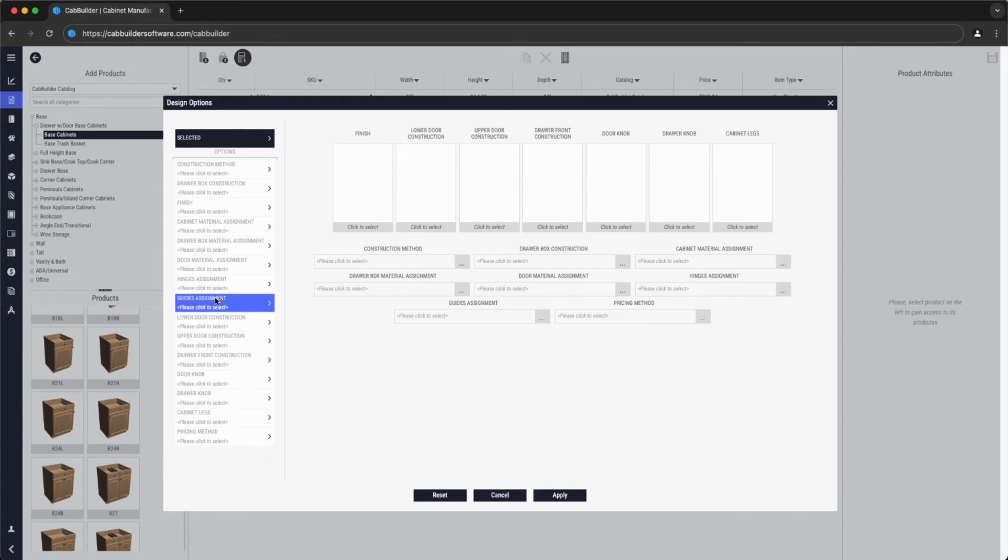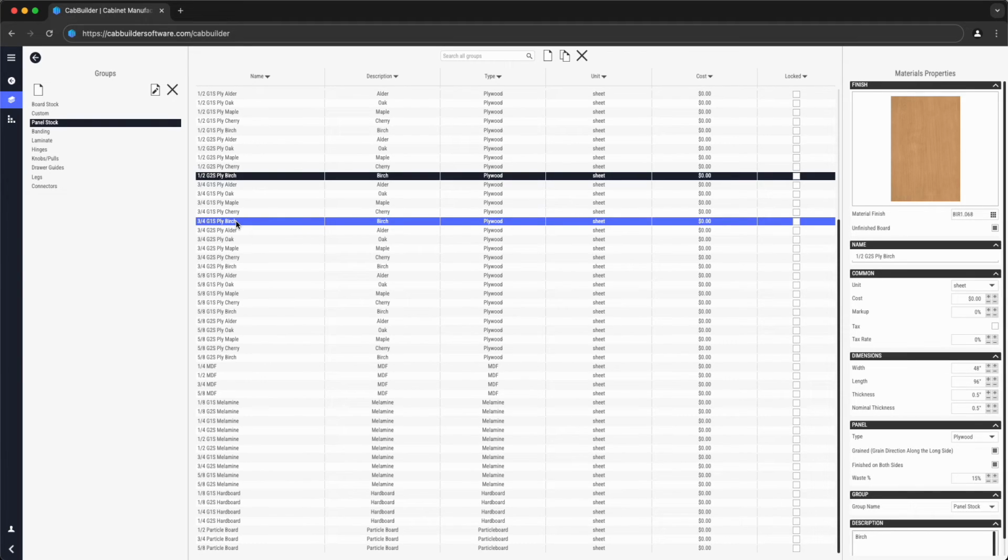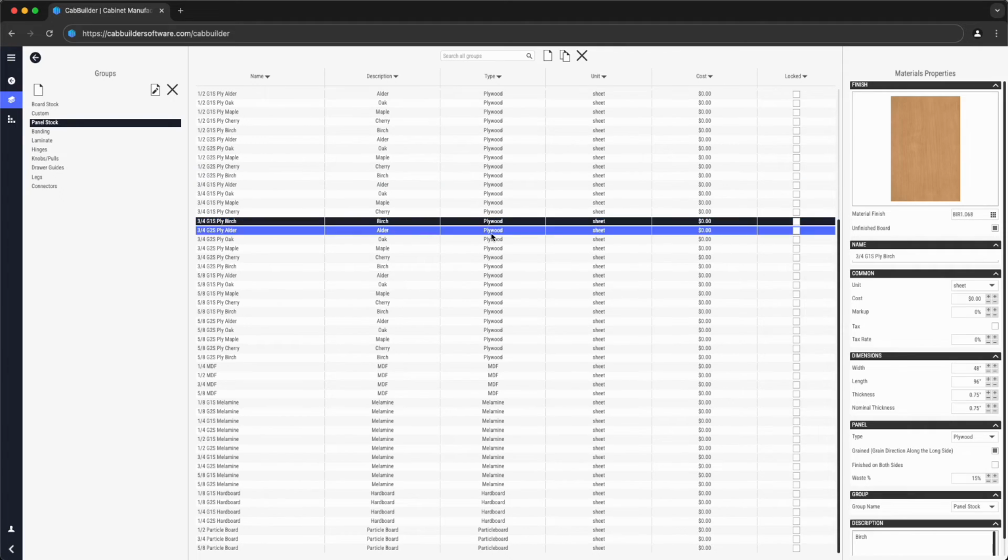and subsequent sub-elements. It is important for the materials used in the cabinet and drawer box material assignments to be properly defined, especially when dealing with the material's thickness. This parameter not only affects the cut list calculations, but also your CNC code coordinates. The grain parameter also has a large impact on how parts will be nested.